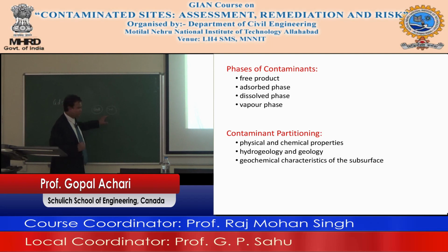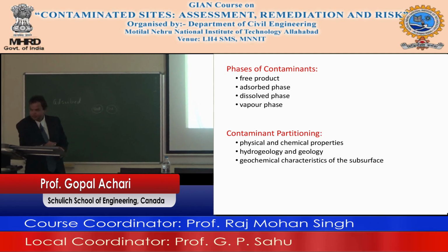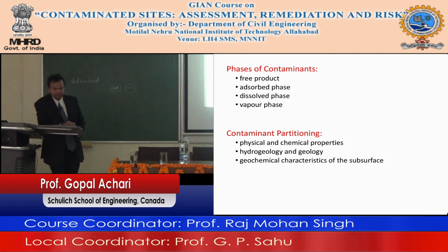If it is unsaturated, there is water, there is air, there are solids. Are you with me on that? So it will be in the vapor phase in that pore space, adsorbed onto the particles, and dissolved in the pore water.